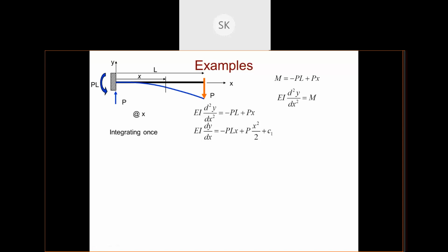What are those boundary conditions? So boundary conditions will be like this. If you see this beam at a deflection, if you see this curve, suppose I'm taking this one as A and this point as B. If you see, at A there is no deflection, right?